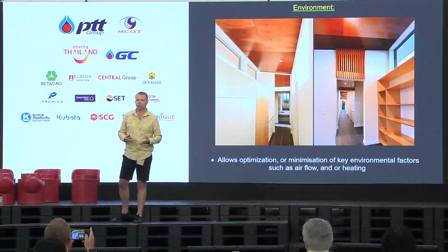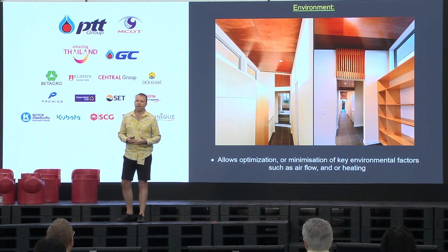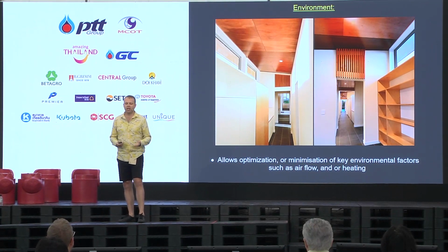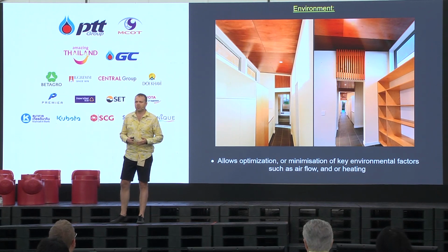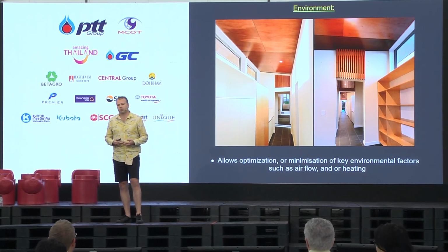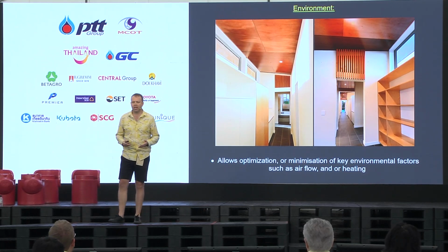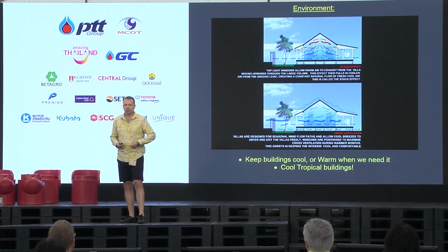And what you see above the corridors are essentially ventilating slats. And they essentially allow passive airflow to circulate through the house. And from that, as a consequence, we don't rely on a mechanical system to distribute air through the house. So it's just using the physics of nature to essentially distribute and cool the house without getting too complicated in the technology that we use.